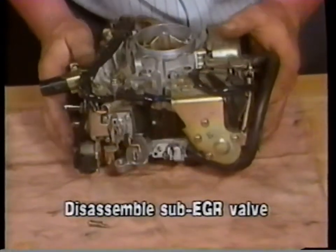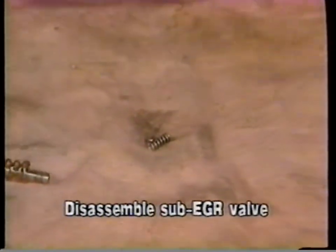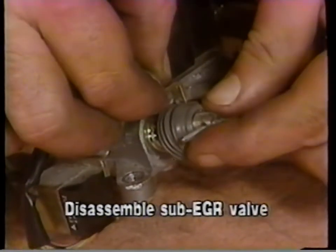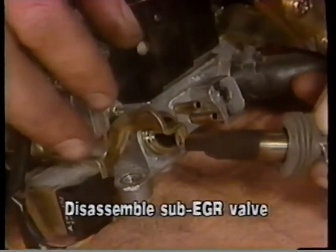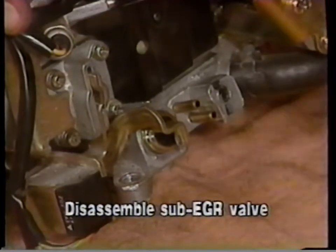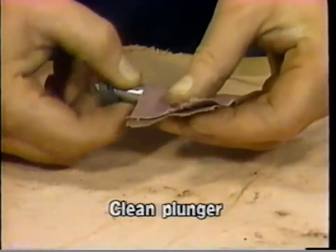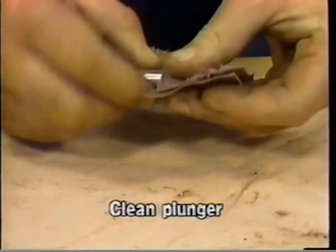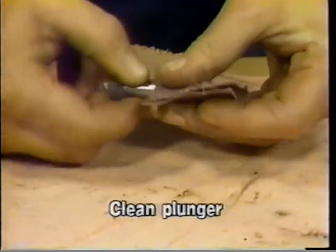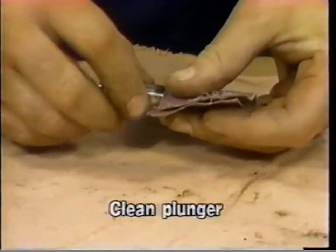Next, carefully remove the steel ball and spring from the end of the plunger and set them aside for later reassembly. Now, remove the plunger from the carburetor throttle body by inserting an Allen wrench through the plunger pinholes and gently twisting the plunger out. After removing the plunger, clean it with a piece of fine, wet emery cloth by twisting the plunger in the emery cloth. Do not use a wire brush to clean the plunger. Scratches from a wire brush will cause carbon to build up more quickly on the plunger.